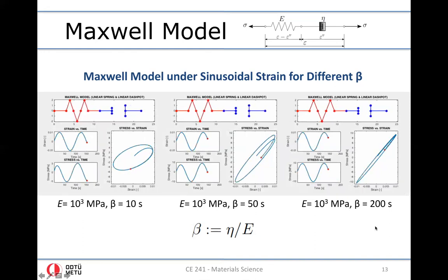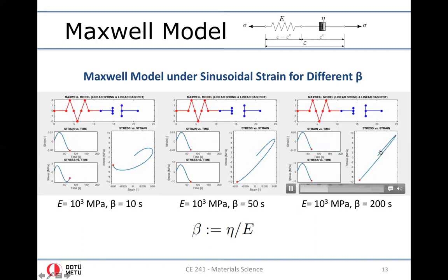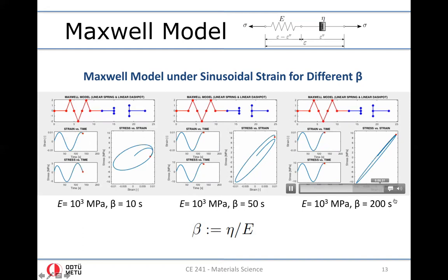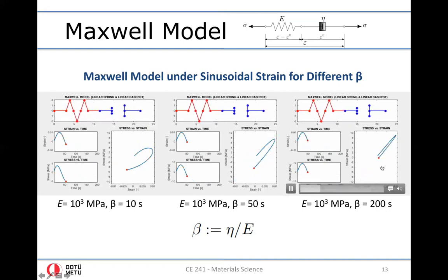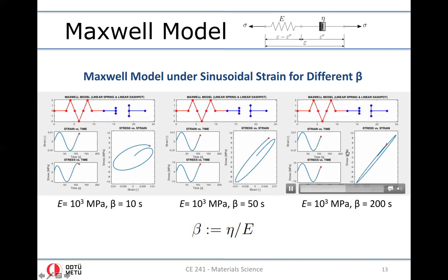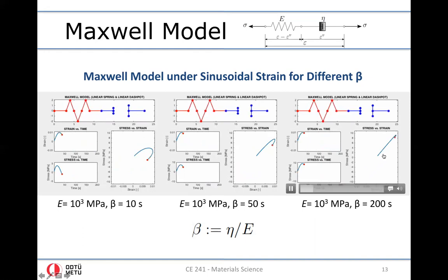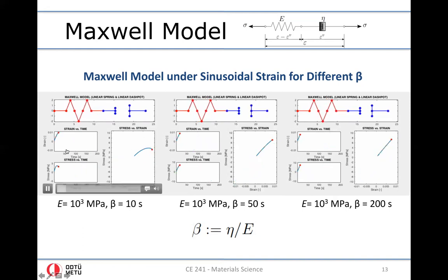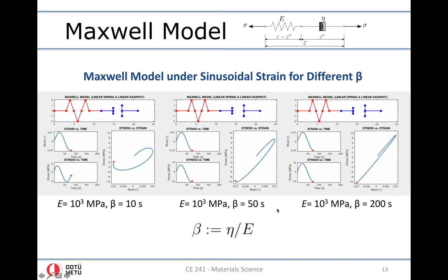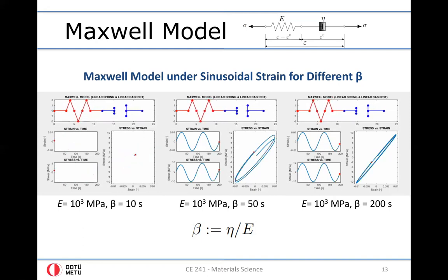loading. Okay, so as you see, when you increase the relaxation time, you don't always increase the dissipation, but you have a stiffer response that you observe for the Maxwell model for the same rate of the loading, for the same loading function, for increasing values of the relaxation time.